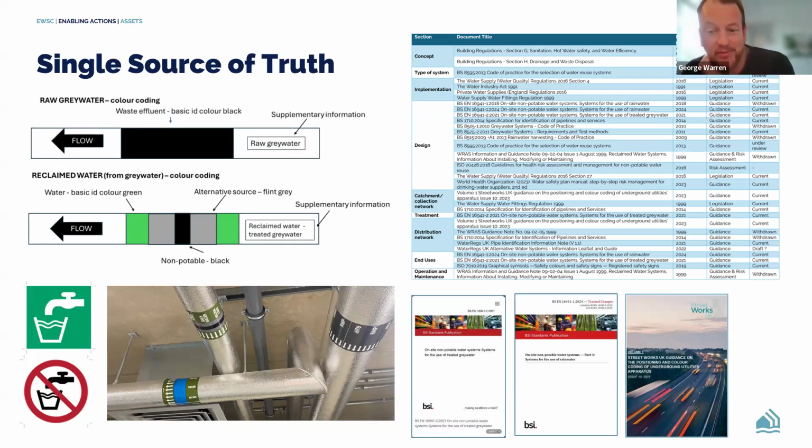For those that can progress with reuse schemes, two recent British standards, for in-house grey water in 2021 and rainwater in 2018, are helpful, but not comprehensive. An older British standard dating back to 2013 also gives guidance on reuse system selection, but is under review. The current building regs refer to water reuse, but if honest, lack detail, although we sincerely hope that new revisions will be proposed. We'll have more on those.